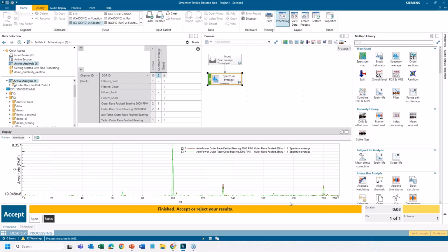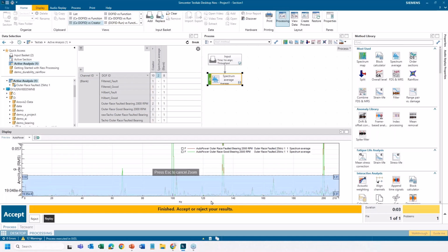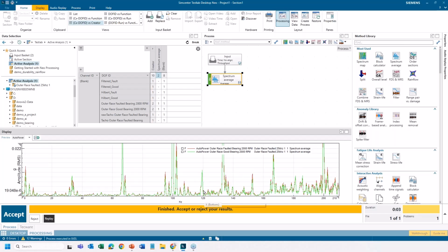So where would we expect to see a peak? Around 121 hertz-ish? Well, first of all, do you see a clear peak there? No, I do not. I don't see a clear peak there either. I see lots of other peaks. And in fact, this fault frequency of the bearing is pretty small. If I was to zoom in amplitude-wise, I'd say there's right around 120 or so there. There is hardly any difference between the bearing with a fault and without a fault at what's supposed to be the fault frequency of the outer race. Would you agree with that?